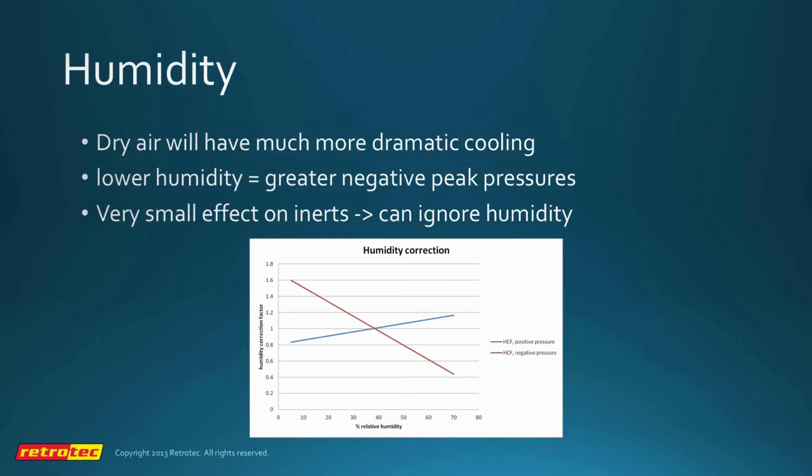So someone was asking, will there be a pressure regulating valve correction in the software at any time? There is one there right now, and yes, it does make a lot of sense. But if you choose Pro Inert right now, you will essentially get the proper peak pressure curve for any of the pressure regulating valves. And in my discussions with Siemens and Tyco, the data that I have so far indicates that the values for Pro Inert for peak pressure will be the same, and in future versions of the software we'll have the trade names of those agents in there.